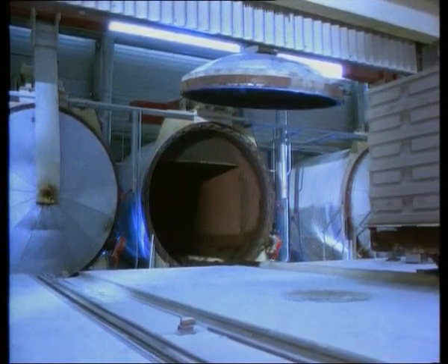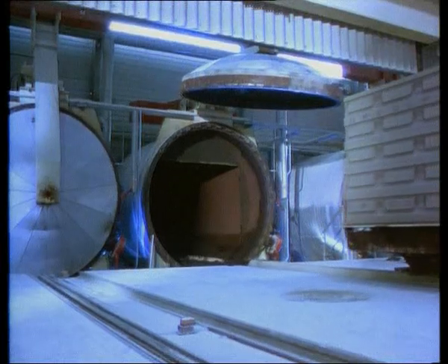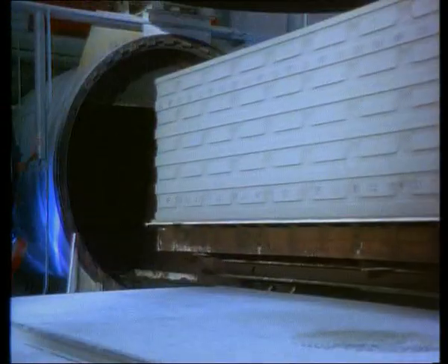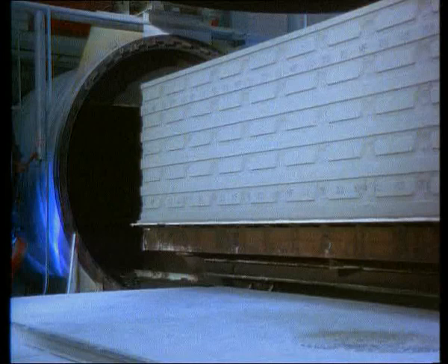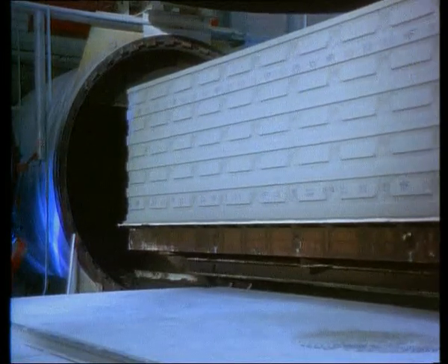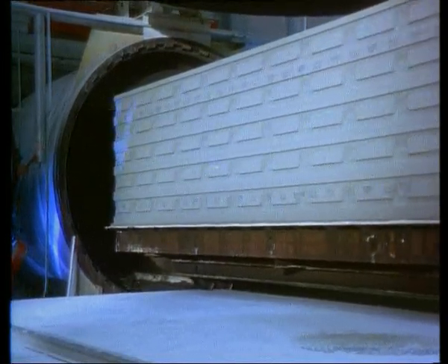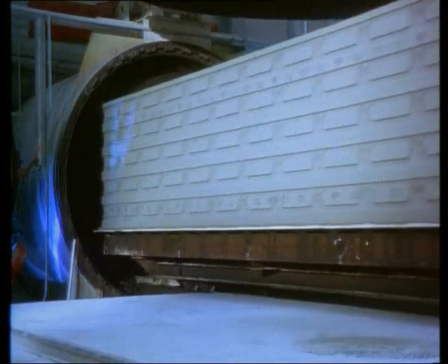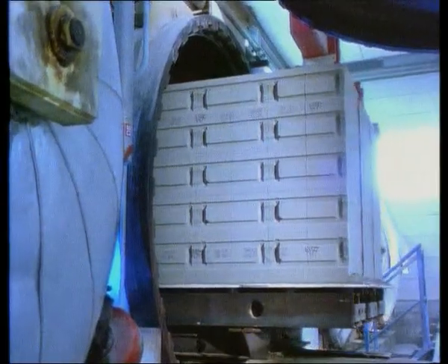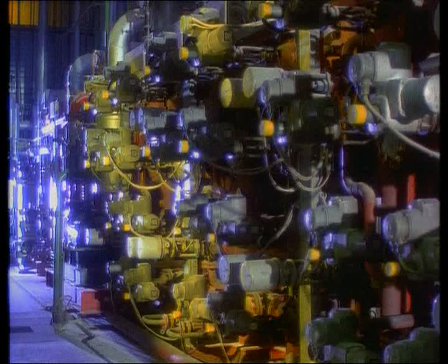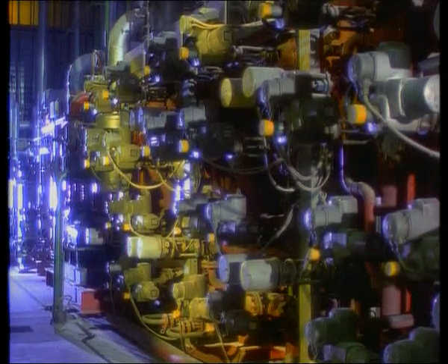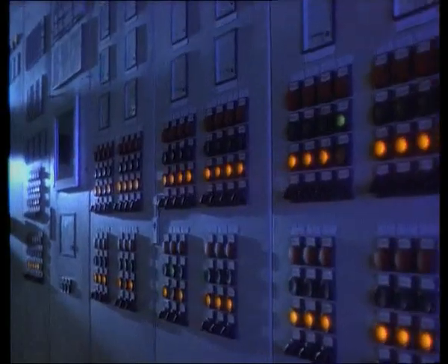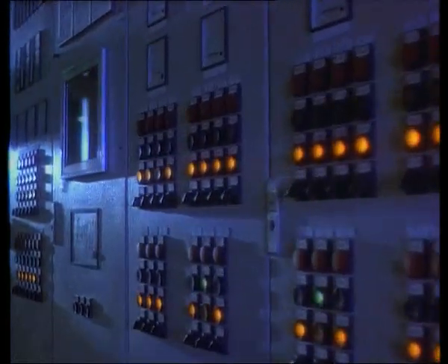The autoclaves are either loaded by means of rope winches or an automatic rod feeder like here in our French plant. This rod feeder pushes a train of 4 curing trucks into the autoclave. In the autoclaves, the YTONG products are treated with saturated steam and reach their final strength in an electronically controlled curing process.